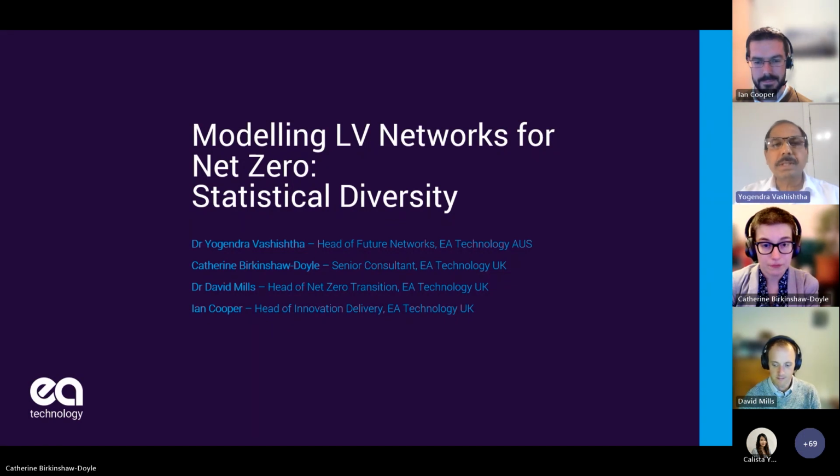That diversity will determine the demand at a given point, and the demand will be used for the network design. That means sizing the cables, sizing the transformer, the protection devices, and also these days to know the hosting capacity, to know the import-export limits.